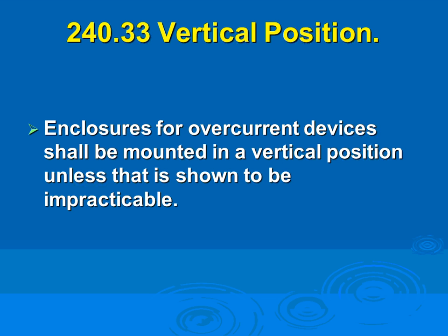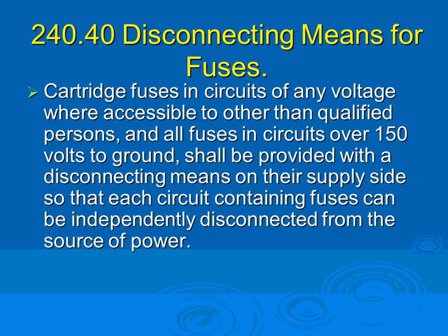What we did design-wise for certain customers, guys, if the switchgear is too high for the room, there was a situation at Mayo Clinic like this. A friend of mine was involved in it. Then you involve somebody like EMI, Electromechanical Industry, and they custom design a shorter than normal switchgear for you, and you can fit it up to 5 feet, and they make them wider this way instead of higher. So it meets your listing, but that's designed by the manufacturer though. That's your refuge, my friend.